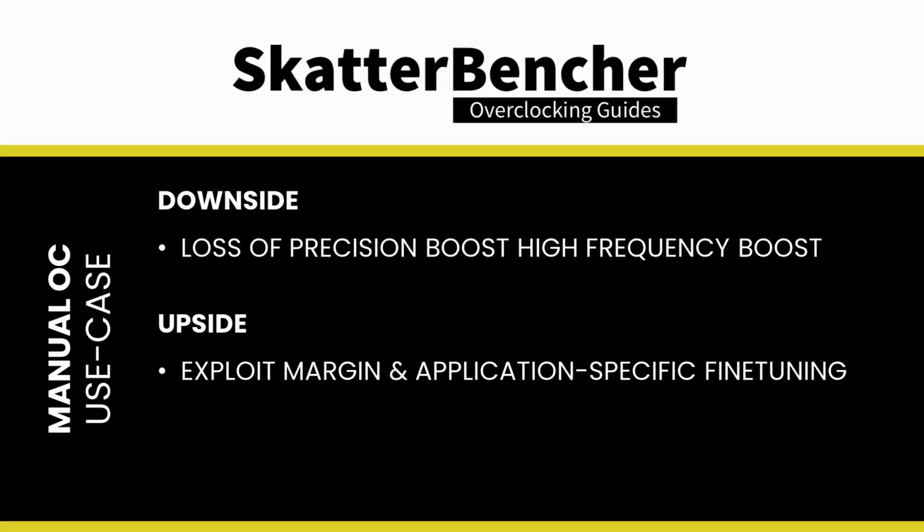However, manual overclocking is not all negative, and it even has some benefits. First, automatic overclocking and frequency boosting technologies leave a little margin on the table. We can exploit this margin and fine-tune for application and system-specific stability when manually overclocking. Second, on AMD Ryzen CPUs, you can set the frequency for each CCX separately.